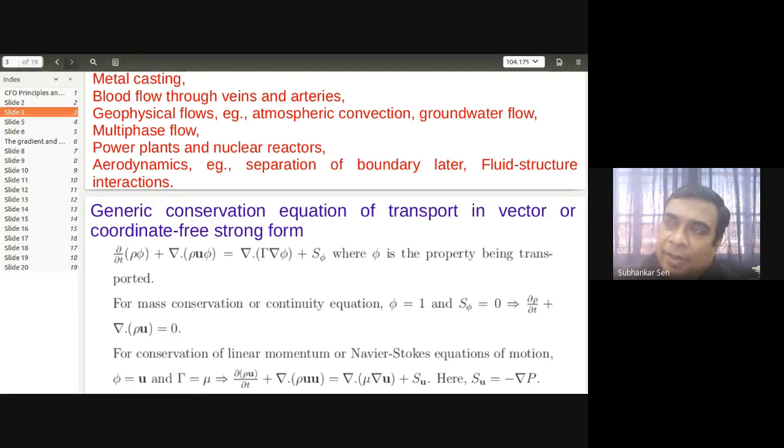It means that if we want to solve a fluid flow problem from the governing equations, we have to go for the approximate approach. We cannot integrate this equation mainly because of the nonlinear convective term. If the convective term is zero, then we may be able to solve this equation exactly by direct integration. So if we are able to solve this equation by direct integration, then we say that we are using the theoretical approach or the analytical approach.